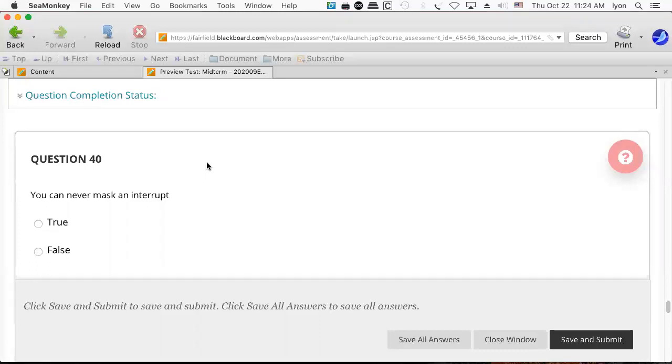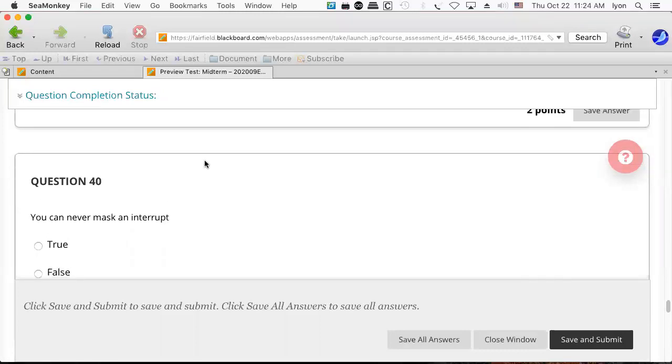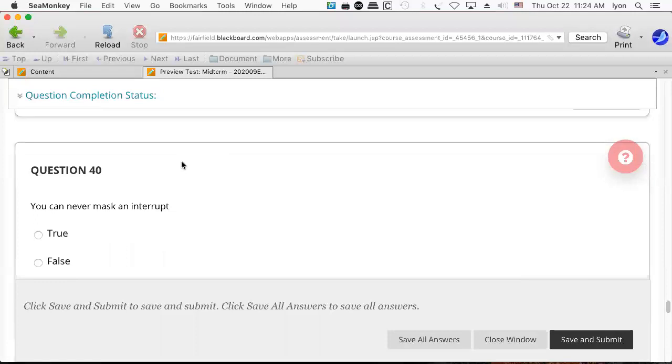You can mask an interrupt. If you do so, you may miss an interrupt. But in fact, by default, interrupts can be interrupted. So you could be in the middle of a long interrupt service routine and get another interruption right in the middle, and then you'll push your address to the stack, jump to the new routine that interrupted you, service that routine, and then when it returns, you pop it off the stack, and you'll be returning the program counter to your address that you left behind.